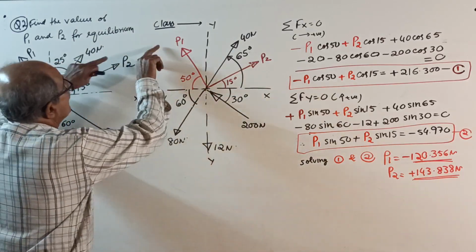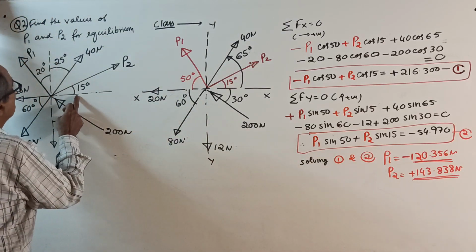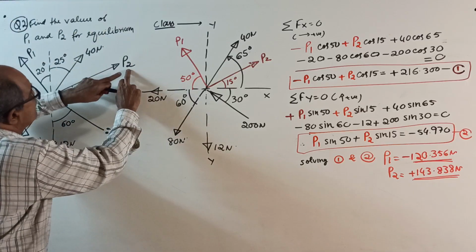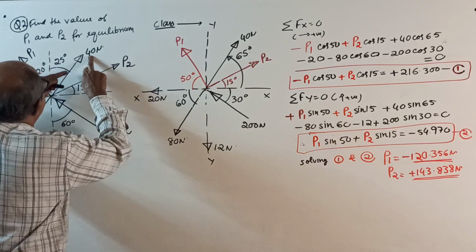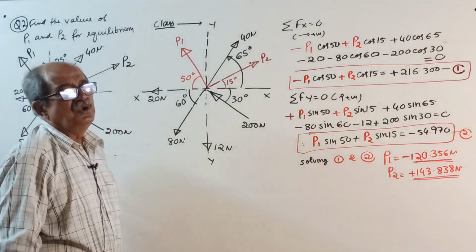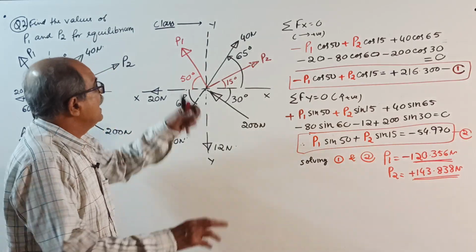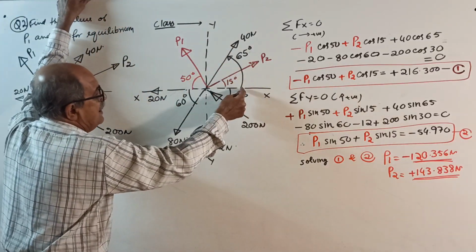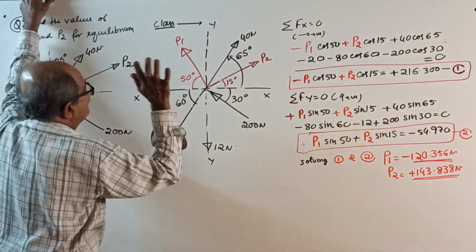Okay. Now, write the sketch once again. This all you have to write if you want. Now, some mixed angles are given. See, for the P2 force, they told 15 degrees with horizontal. I made it red because it is unknown. For P2, the angle is 15 degrees. For the 40 Newton force, they told 25 degrees with vertical, yy. I told you, for an easy approach or to avoid confusion, mark the angle with horizontal. This is 15 for this one. Again from xx only, this angle is 90 minus 25, which is 65 degrees.